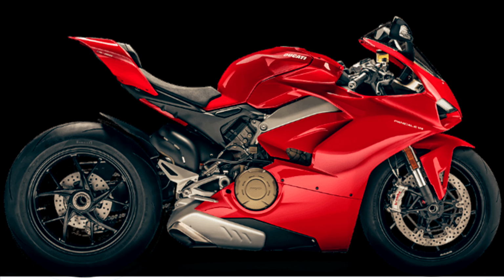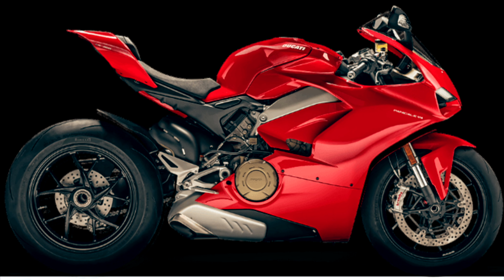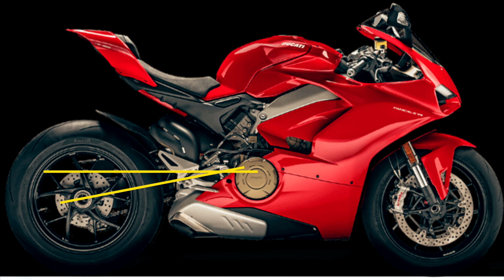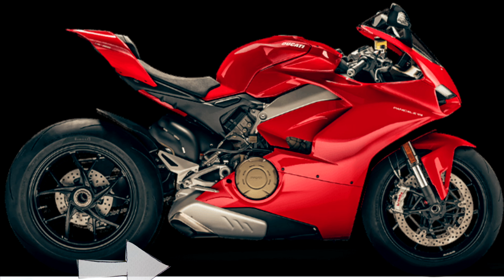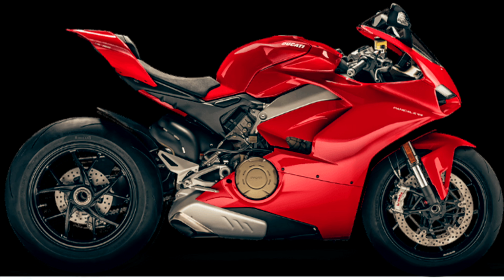On a motorcycle with a chain, there are two primary ways to achieve anti-squat. One is to put the swing arm at an angle. Look at where the swing arm is connected. This is called the swing arm pivot point. Now look at the rear axle. Draw a line through the pivot point and the rear axle. Then imagine a horizontal plane that goes through the pivot point. The angle between the plane and the line is the swing arm angle. Imagine what happens if the rear wheel is driving the bike forward. Because of the upwards angle of the swing arm, the suspension is extended.